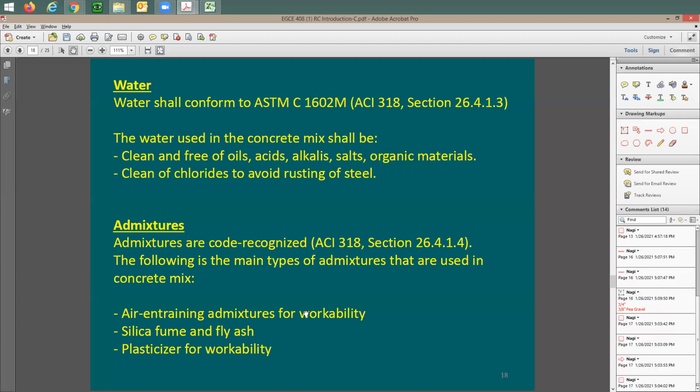So what happened, you have this maximum amount of water that you can add to the concrete, which is roughly about maybe 50%, maybe 45% of the cement weight. Now, the concrete is going to be very stiff. So now you'd like to put it, and you need to have lots of vibration. It's going to be very tough to set the concrete between forms and to cast it.